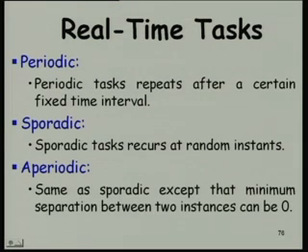There will be a clock which gives an interrupt after 100 millisecond, and based on the interrupt the task of sampling the temperature arises. There has to be a clock in every periodic task, and as soon as it gives an interrupt at periodic times, the task is getting fired.